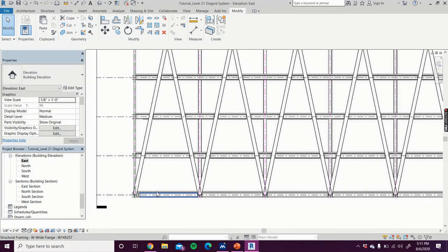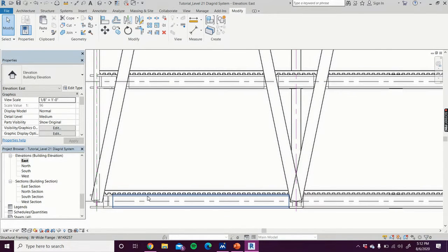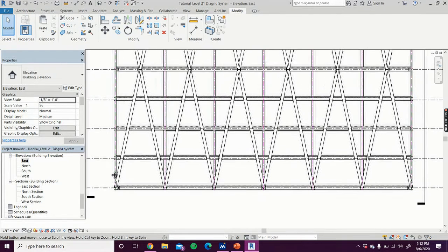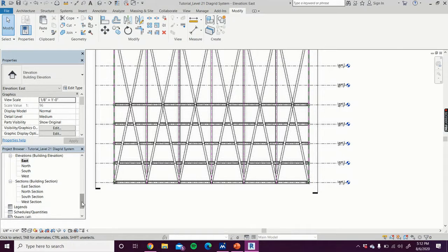And make sure you have all these floors. I placed all my beams centered with the grid line, and then I just raised the floor by 1 foot 1 inch so it appeared above all of the beams, just for appearance, but you'll obviously have to edit that based off of your beam sizes and where you want these beams to lay according to the grid lines. So once you figure that out, you start copying and pasting to the above floors. So let's begin.